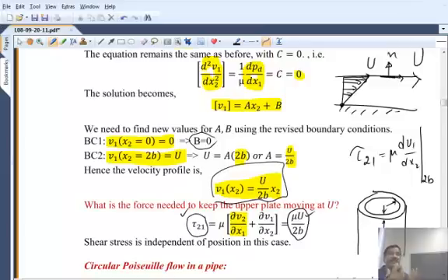So it's as if I take these two parallel sheets and fold them so that they become circular, and then I have a continuous, infinitely long parallel plate that can simulate that condition because it just keeps going forever. That's a very clever design. What you need to do is mount the outer cylinder onto a motor so that you can rotate it at a constant speed. That way you know what the velocity is, and you can measure that.